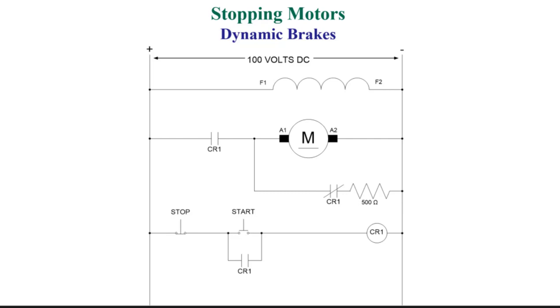The more current that flows in the generator, the stronger that counter motor force is, counter torque. If you are at a stoplight in your car, and you have the fan running, your lights on, windshield wipers, and the vehicle's idling at a certain speed, and now I turn on something that's a heavy load, maybe some fog lights.